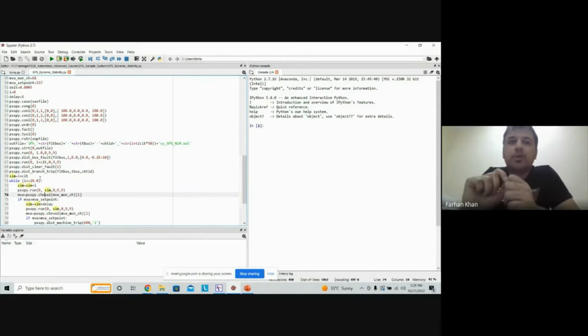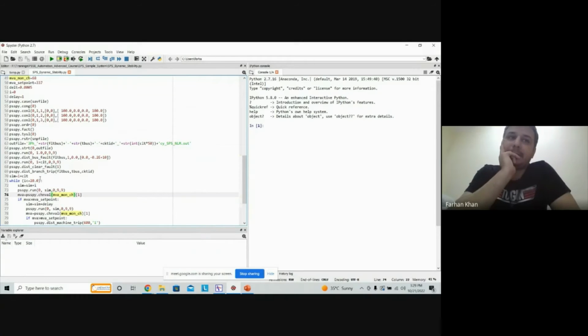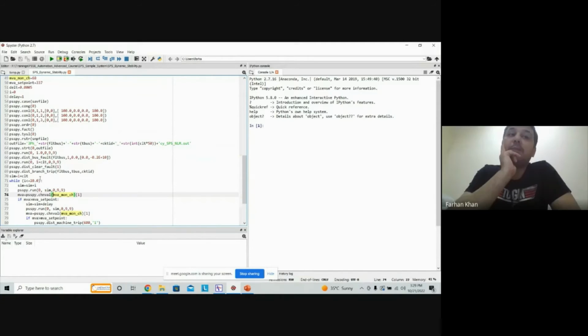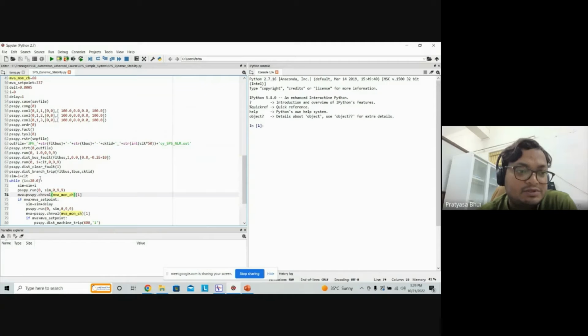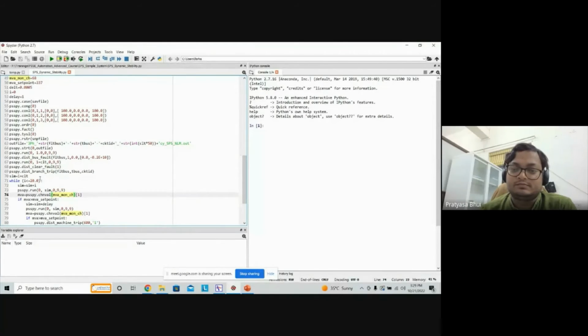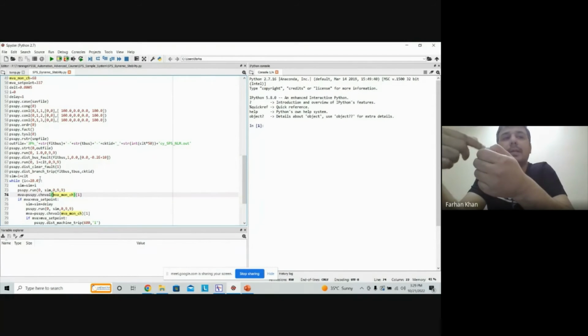And then I am going to monitor my channel. So this sim is 1 plus CLT, and CLT is your clearing time, right? If it is 0.1, then sim is 1.1 at this instant. And then you are running the loop, so sim equals sim plus I. In my case, my starting I is 0, so this means I am still at 1.1. So from where I created the disturbance, now I'm starting to monitor my channel.